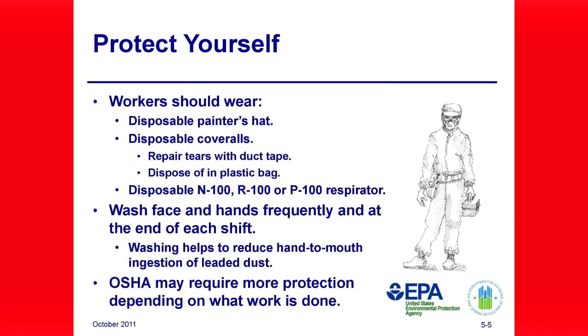Protect yourself. Workers should protect themselves. Painter's hats are an inexpensive way to keep dust and paint chips out of the worker's hair. Painter's hats can be easily disposed of and should be disposed of at the end of each day or at the end of the job. Disposable coveralls are a good way to keep dust off the workers' street clothes and reduce the chance of carrying dust away as they come and go.